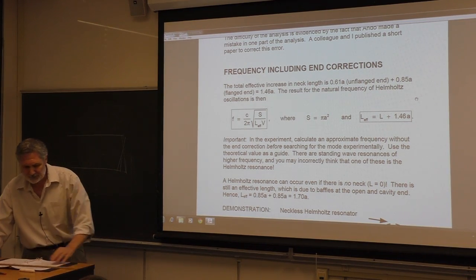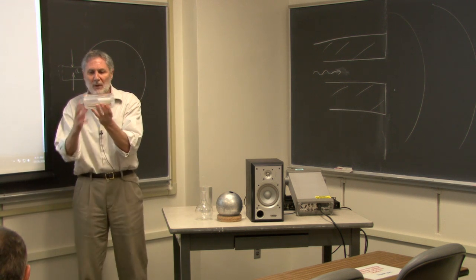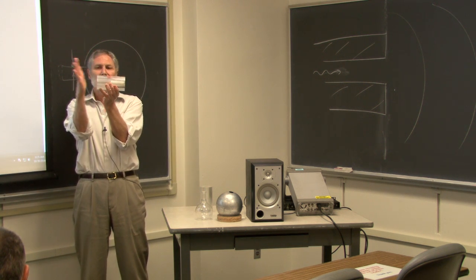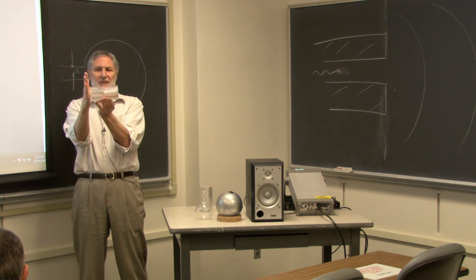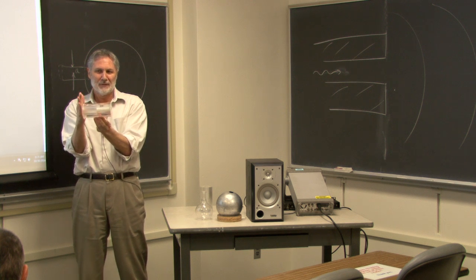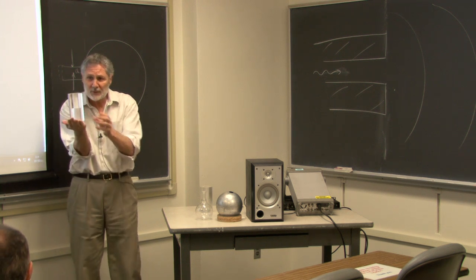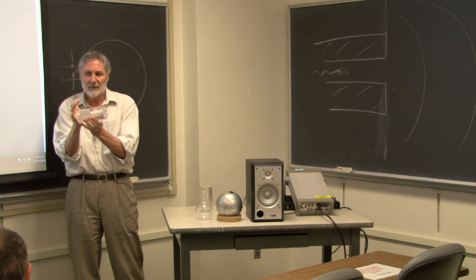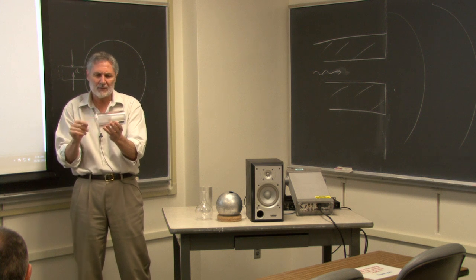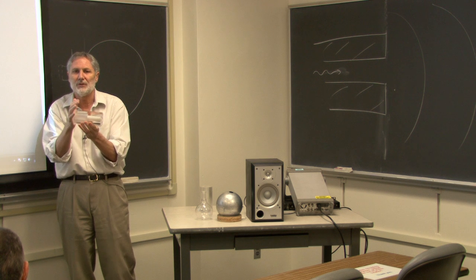I realized that I didn't explain to you, it's not in the notes, why is this frequency greater than that frequency? What does this look like to you, approximately? Starts with H, 2 words. First word is Helmholtz. Second word is resonator. It looks like a Helmholtz resonator, right? And you know that the wavelength is going to be big for Helmholtz resonance, right? Now, it doesn't really meet the requirements of having a small neck compared to the cavity, but still, it's roughly a Helmholtz resonator.